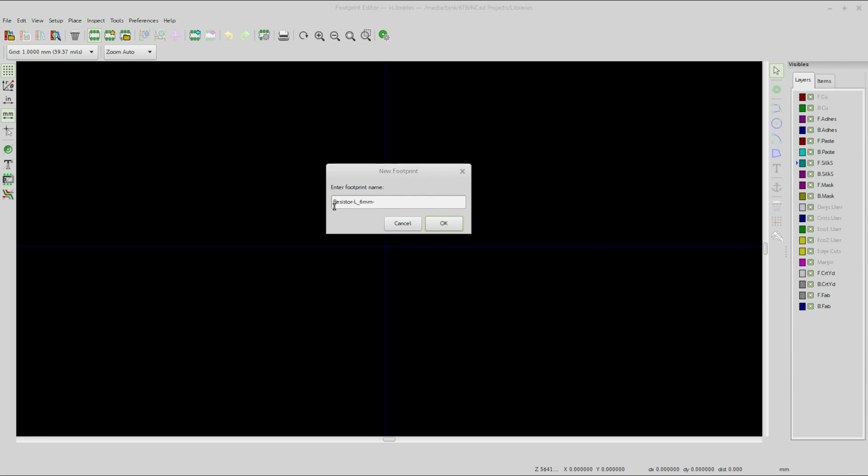How about 10 millimeter? I'm not going to do a width because it's too small. I don't really care about it. And I'll say 2 millimeter. You can come up with some secret code, but I'm just going to write spacing. It seems to work for me. So you see what I'm doing? Alphabetically, you'll find all the resistors next to each other. And if you keep the same naming scheme, at least up to about in here, it'll be dash L, and then you just go scrolling through there looking for the length of resistor that you're after.